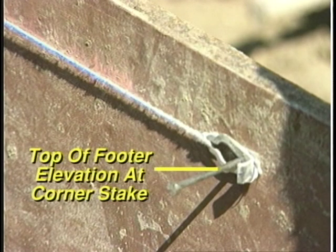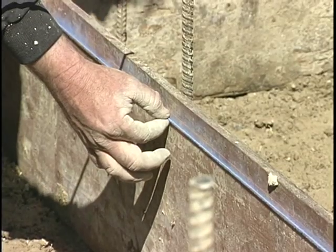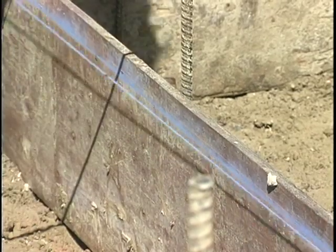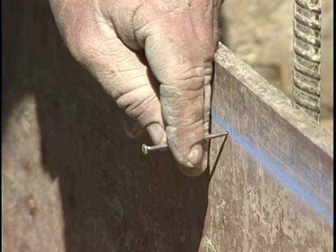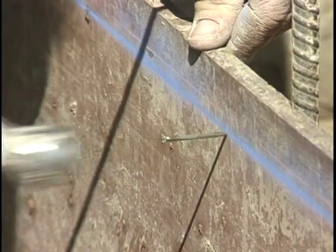Establish proper elevations at all corner stakes. Then run a chalk line inside the footer forms between these points. Snap the chalk line on the inner surface of the forms. This will give you an elevation guide for pouring the concrete to the correct height.